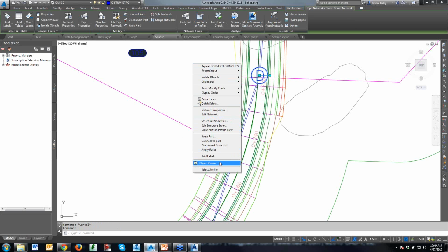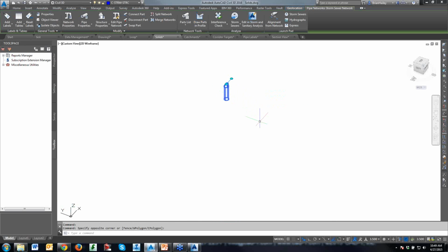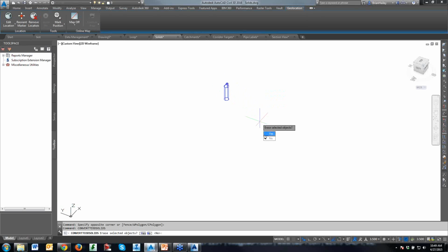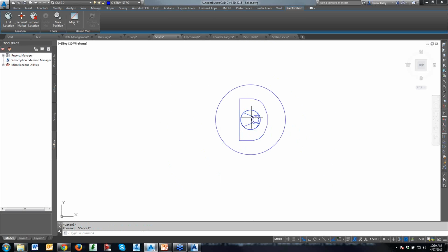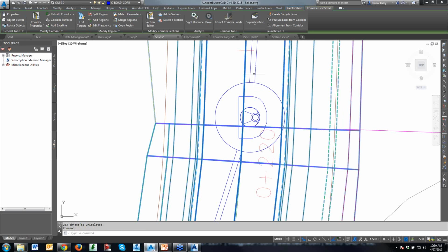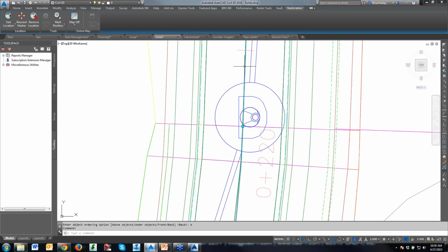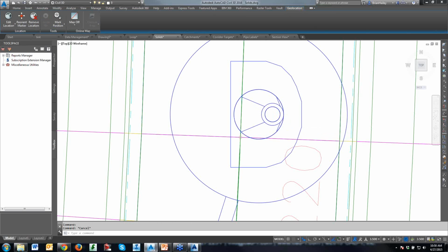Hang on, I might need to be in a selected objects. Let's pull that off of the 3D view, and now let's do it. Yep, so there it is. So there's the 3D solid now. And as you can see, just a piece of it is touching my centerline alignment. Okay, so just that piece of it. If I were to cut a cross section through it, that cone isn't going to come through. Good grammar, Brian. Isn't going to be shown in there.